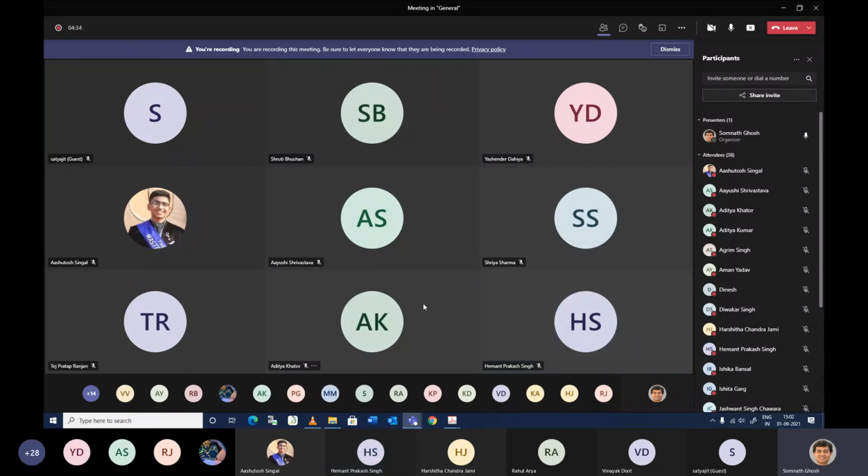Hemant. Yes, sir. Okay, so it's mechanical energy balance, right? The conventional Bernoulli's equation, which we understand, is basically based on a fluid which has no viscosity. That means it's inviscid flow, right? In that case, we derive the simplest form of energy balance equation, that is known as Bernoulli's equation.